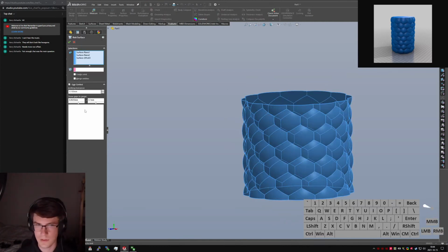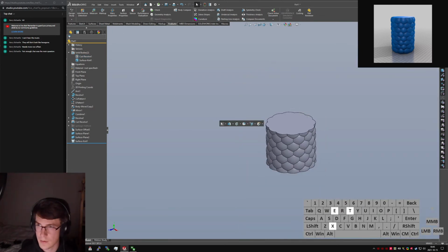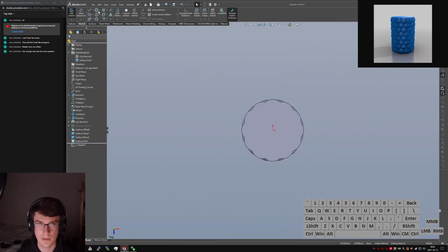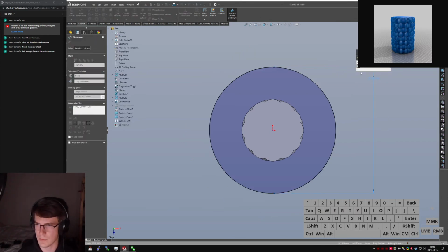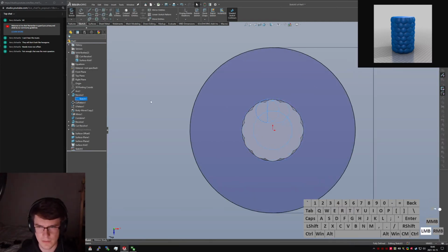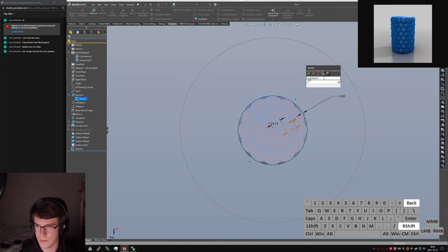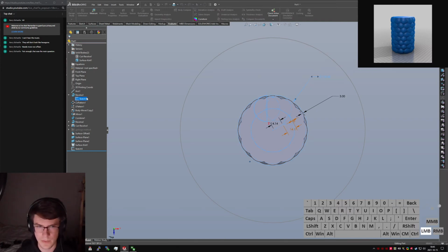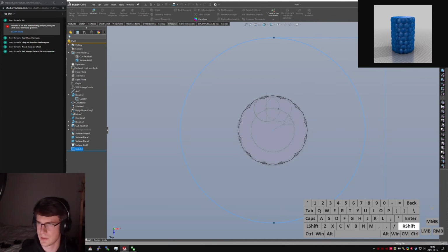Hit surface. Create solid. So now I've got two solids. One of them slightly larger on the outside than the other. Extruded boss. Top plane. Equals 200. Well, actually, can I say 200? What was D1 in that first sketch? Exit sketch. Yeah, don't make me extrude that just yet, please. D1 at sketch 1. We'll call this OD. OD at sketch 1. We'll call this control sketch or something. C sketch, a little shorter as well. Let's call this 2 times OD at C sketch.